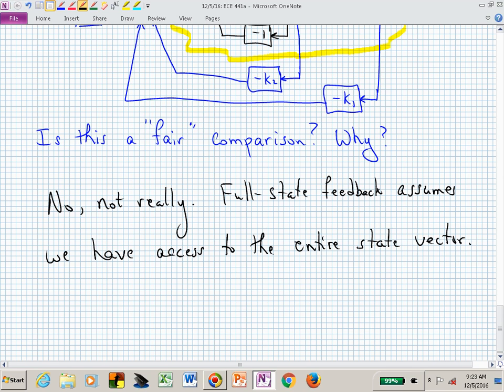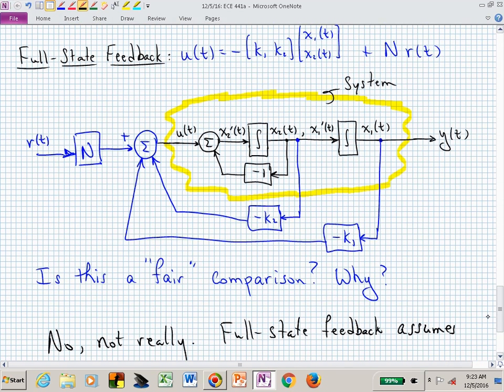And that actually might, in this full state feedback case, unless we have a really good knowledge of our A matrix, B matrix, and C matrix, this N matrix or variable may not give us the DC gain of 1 that we would like to have had if there's some uncertainties. And our tracking error might be bigger in full state feedback than in output feedback.